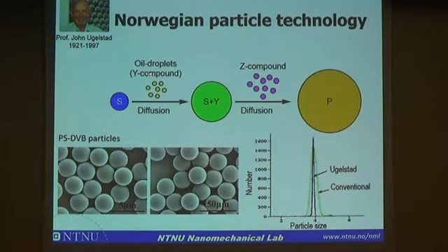The key process is that we start from a uniform seed, but different from seed polymerization, we have multiple swelling processes. In every process, we control the swelling ratio of the monomers. Then at the last polymerization part, we get a uniform size of the polymer particles. These particles usually have a cross-linked structure.